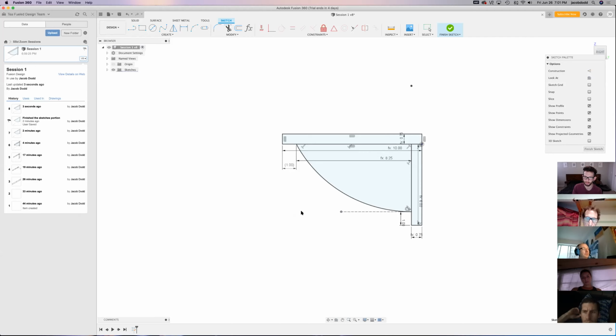Right. So for example, this construction line, we can move it back and forth. It's locked in the angle that it's at, but we can still kind of change the length of it. So if we were to set the dimension of this line to be whatever it is, 11.1, we then cannot go into the constraints and say that actually this line equals the same as the top, because it will give us an error. That little error that popped up, that's what I've seen a bunch. So it's just telling you there's something else that's blocking that.